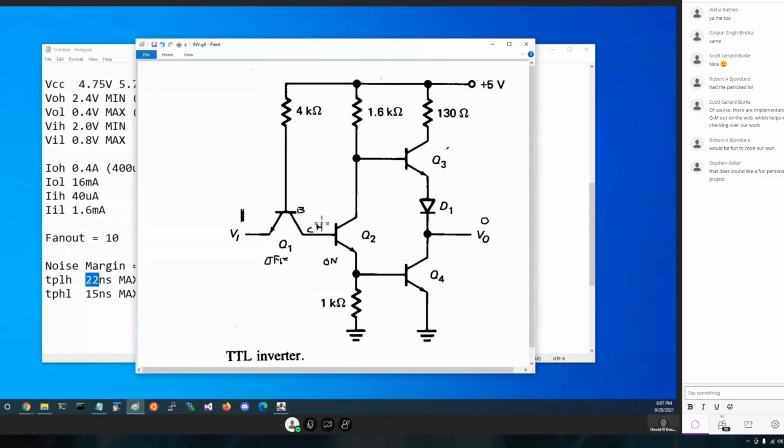The collector is an N. This is a P. That's a diode. I can see right through that diode, through the resistor, up to the 5 volts. Meaning this transistor is definitely turned on, and this is pulled down to roughly 0 volts.